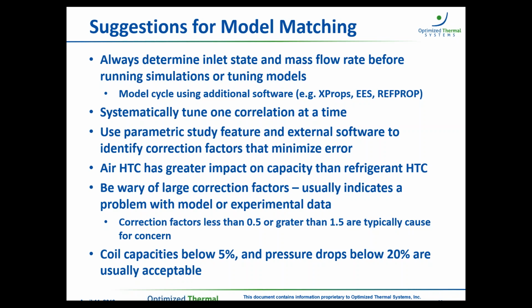We use airside heat transfer coefficient to tune our heat exchanger performance in terms of capacity. This is an assumption that we make. We could alternatively tune the heat transfer coefficient on the refrigerant side, but the air heat transfer coefficient has a greater impact on the overall performance of the heat exchanger. So we find that to be a more effective and simpler approach to heat exchanger model tuning.